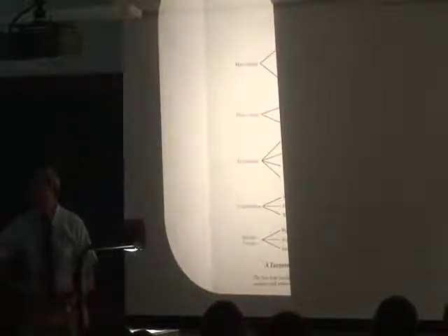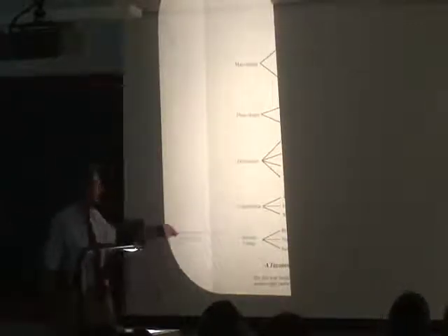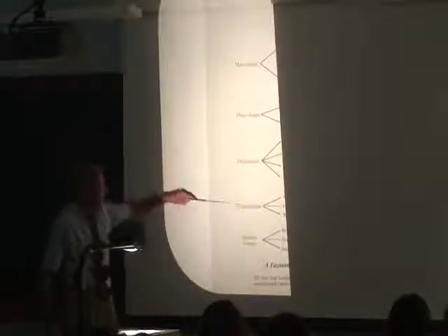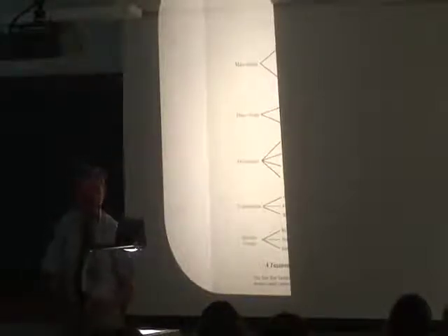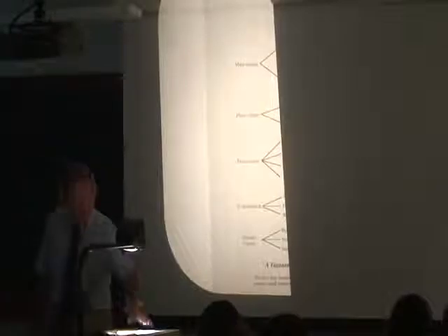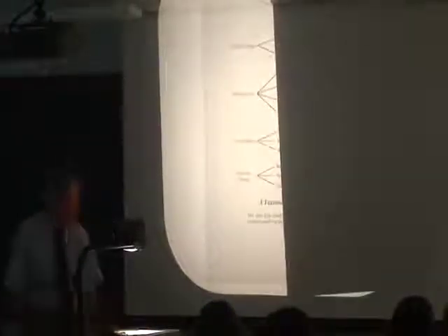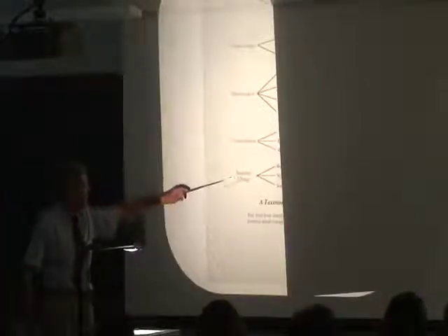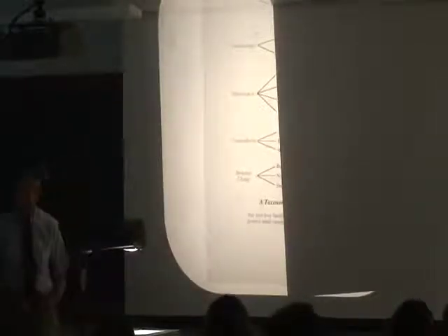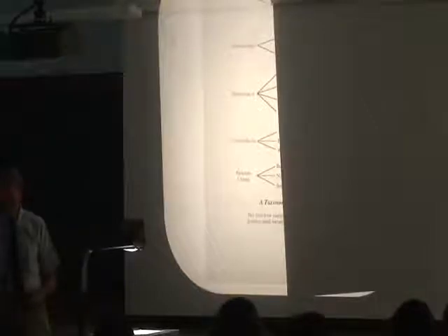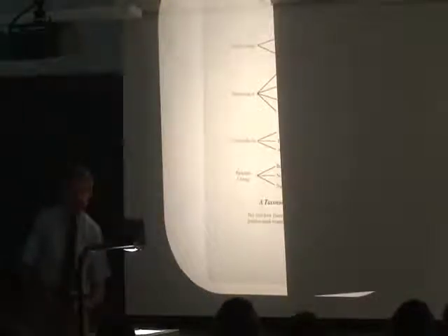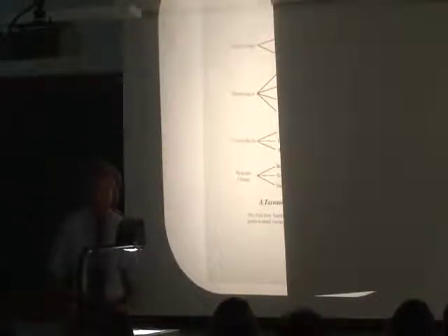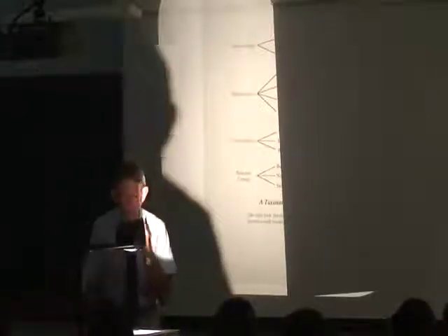You bend sheet metal, you force things through dies, you bang on things with hammers, as in piston rods to strengthen them, etc. There are consolidation processes. You put together metal powders or you make fiberglass-like compositions and so on. Then there are structure changes, and these really affect the internal structure of the material. Surface hardness, directional grain properties, so the material becomes anisotropic, and so forth.